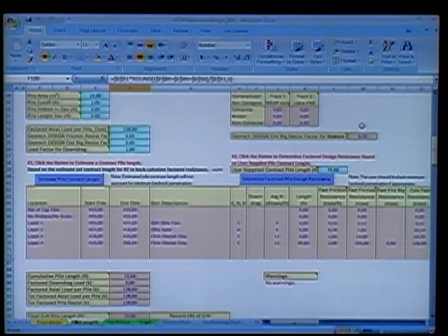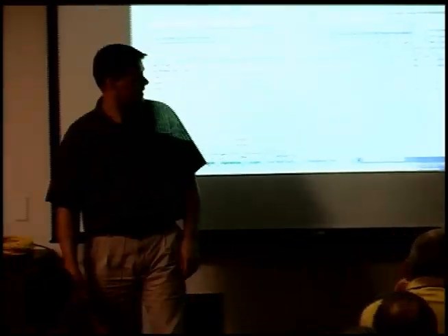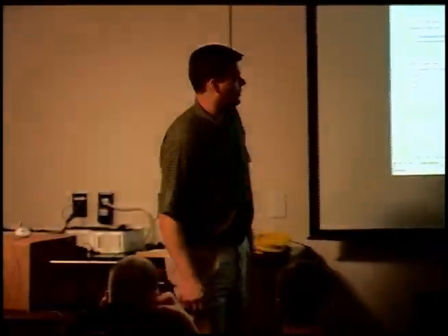So if you work with the factored values, then you know that whatever you put up in the soil chart way above got multiplied by this resistance factor to reduce it down. As I show here, this is the kips per foot, so it's reduced down from whatever was above, in this case only by 0.65. But if you had end bearing and rock, it would reduce it by the 0.7, or whatever you put in there.